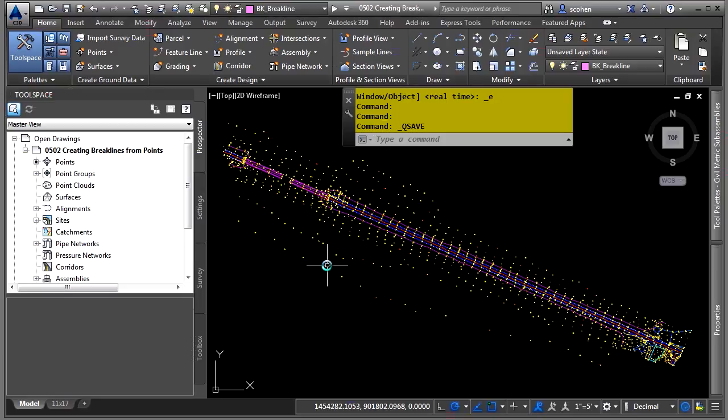There are a few methods that you can use to establish breaklines in a surface. Breaklines instruct Civil 3D of points that have a linear relationship with each other, and two or more points are required to define a breakline. Let's examine how to create breaklines that can be added to a surface for proper triangulation. Along with creating regular polylines, you can actually use 3D polylines as well.